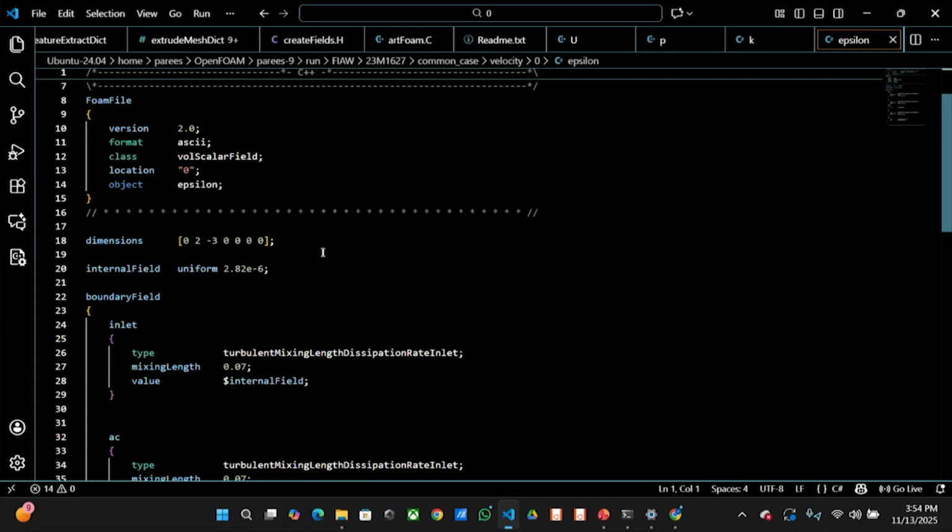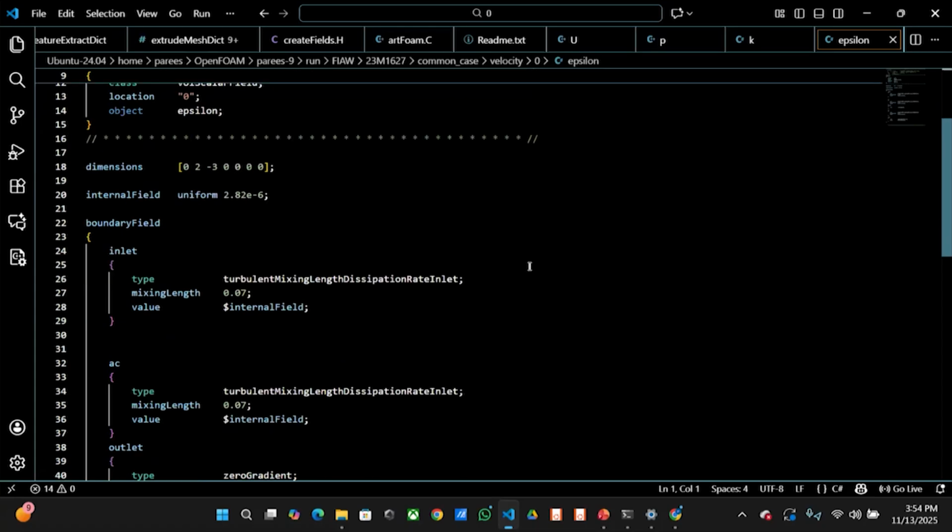Let us say we have to provide some dummy values to OpenFOAM before actually starting to simulate. Because if we are giving 0 here and the value is drastically changing at the inlet patch or the particular patch you are interested in, there might be some issue in your solution, and either OpenFOAM might crash or it will give you some errors.